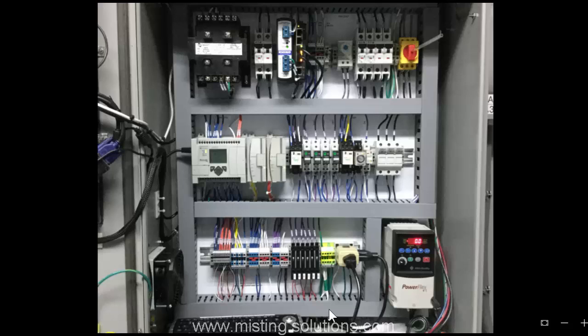Now some of these, as I discussed, are power distribution terminal blocks. And what I mean by that is this AC terminal block here has one 24 volt AC wire coming off the power supply, off the transformer, comes down and ties to this terminal block right here. And then they're all jumpered together, and then these purple wires, 24 volt AC wires, go into the top of these cube relays here, which is the power for the solenoid valves. So again, 24 volts AC is solenoid valve coil power.